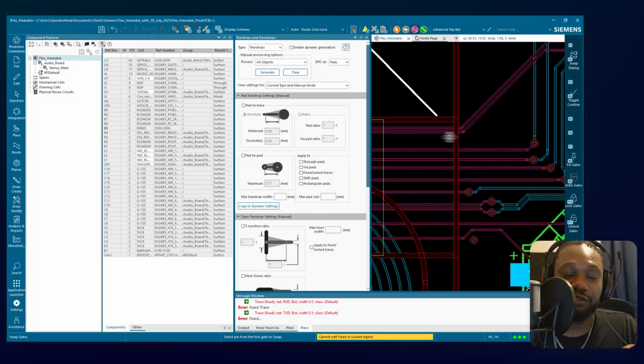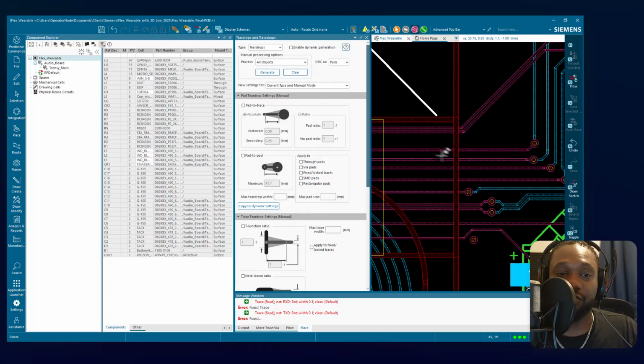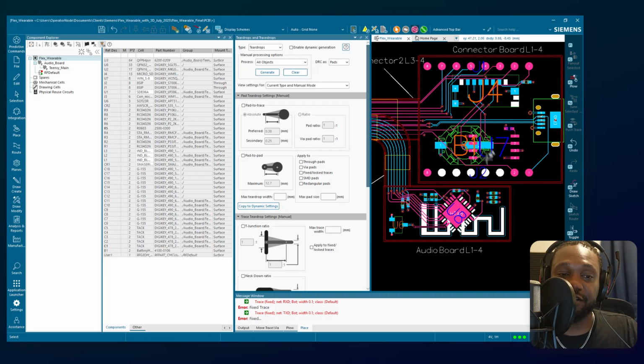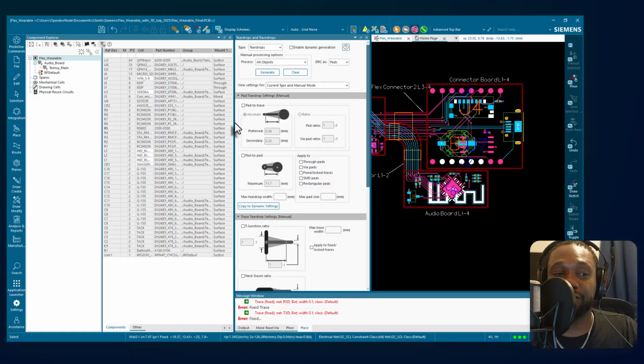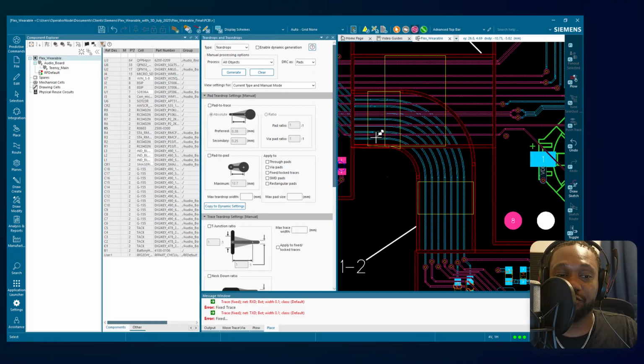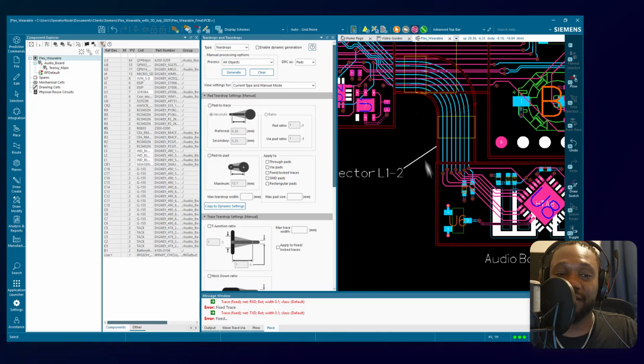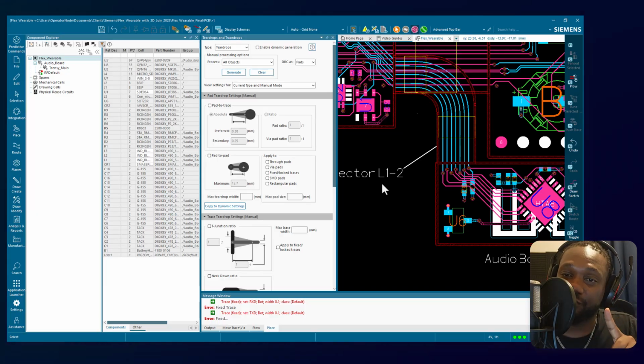So I like that it has all of this for routing, and then you can actually route in groups as well. So if you select your nets and your routing, you can do sketch routing and route in groups, meaning multiple nets at the same time. Set your destination to where you want to route all of your nets. This is especially useful for DDR signals, like a group of DDR signals like these. And then the software tool will automatically just route all of them according to the constraints, signal propagation, delays, and everything that you set in the constraint manager.